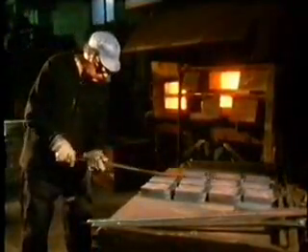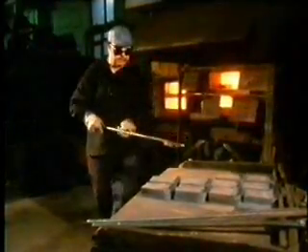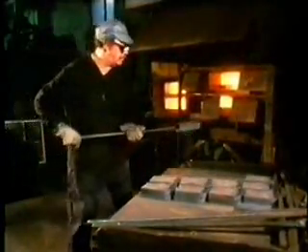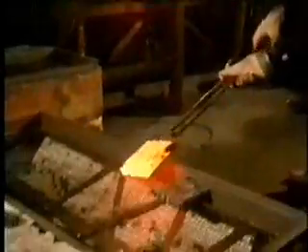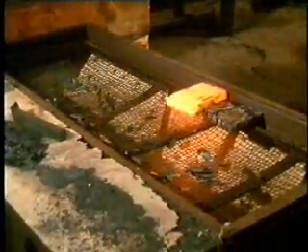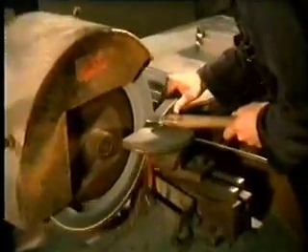Heat treatment is perhaps the most important stage in the production of high-speed steel tools. It's from heat treatment that the tools derive their cutting properties. The first stage is a preheat, in which the tools are raised to 850 degrees centigrade. After a few minutes, they're removed and placed in the main chamber at 1200 degrees centigrade for a further period. They're finally quenched in a stream of hot air. Once cleaned, there's one last grinding which imparts a good cutting edge.